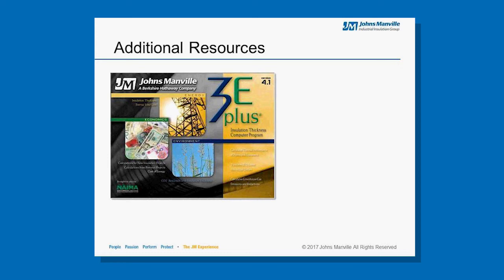So what you can see right now is the NEMA 3E Plus tool. Now, this is free and it's available from NEMA, but what we've actually done is we've partnered with NEMA to give you output numbers that are specific to JM products. While the standard NEMA 3E Plus tool is designed to help you establish approximated insulation thicknesses based on generic material performance, the JM NEMA 3E Plus tool has product information that's specific to JM products. So if you know you want to use or specify a JM product, you can use this tool to establish the appropriate insulation thickness for the specific JM product that you'd like to use.